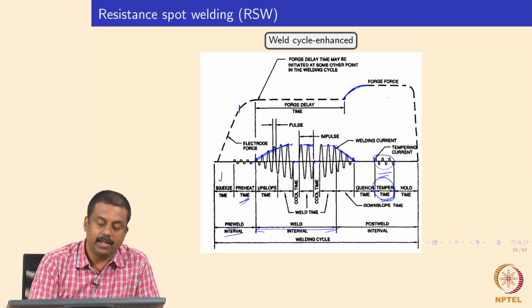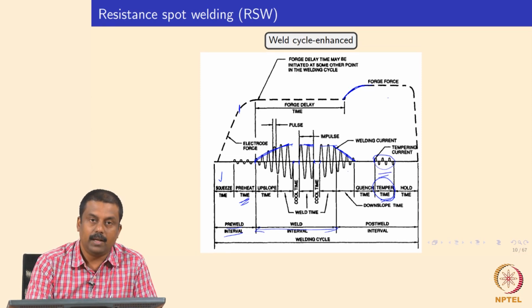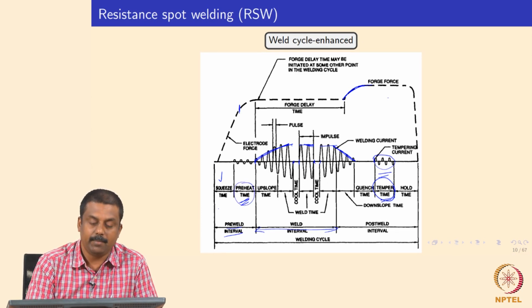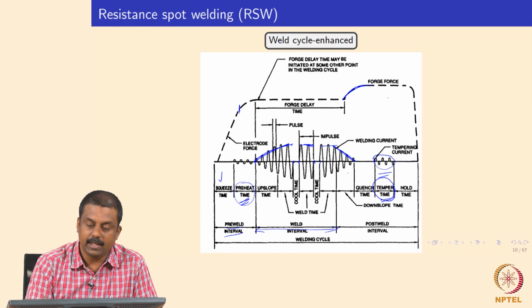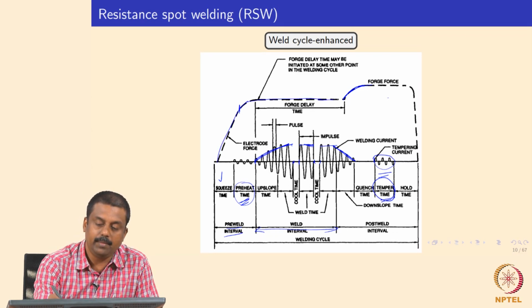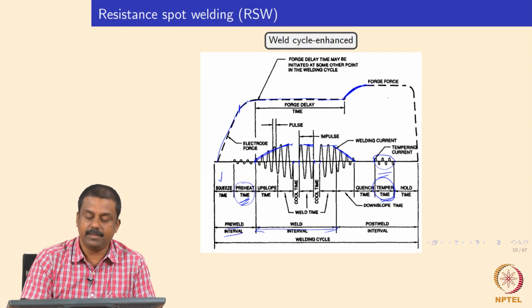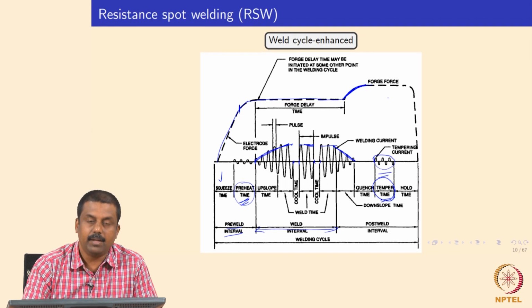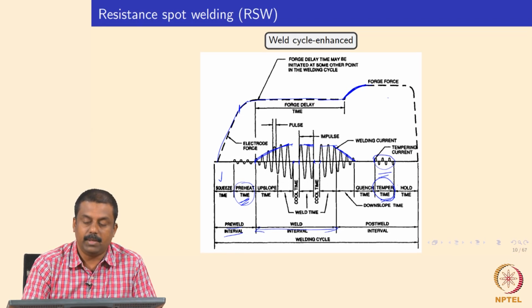Or if you want to reduce the cooling rate at which the welds are cooled after welding, you can also do preheating by applying some small short pulsing before the application of the actual welding current. You can also change the loads based on our need. In this case, in a typical cycle, we also have an increasing load when the weld nugget is cooled to mitigate the residual stress. All of them can be used in our favor to modify the weld thermal cycle.